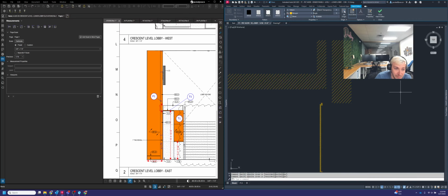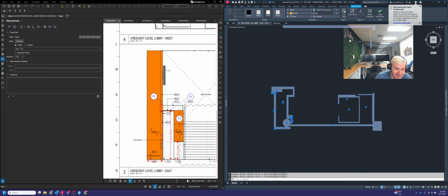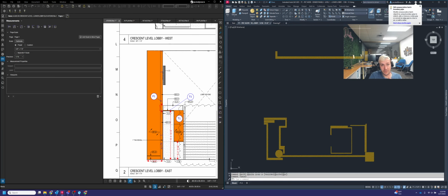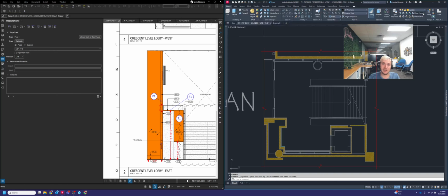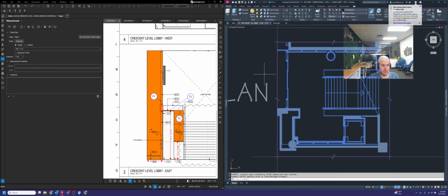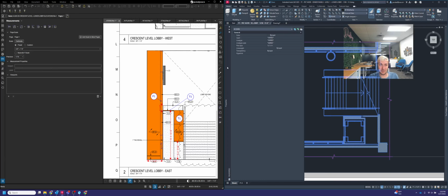There are other ways to do this too. I can show you other methods of how to do that as well. Let's say you did have all of this stuff here and maybe you didn't want to use that isolate command. Highlight your entire plan view and go into your properties pane. Because another quick way to only show the wall hatch is to go up here to this lightning bolt called quick select. It's up in the right hand corner of your properties.